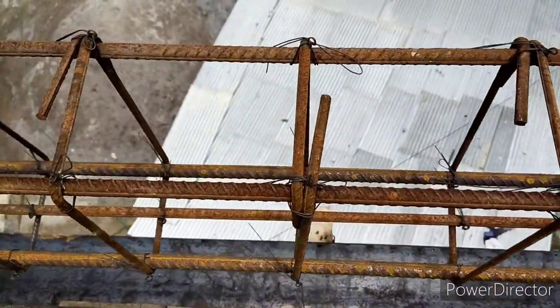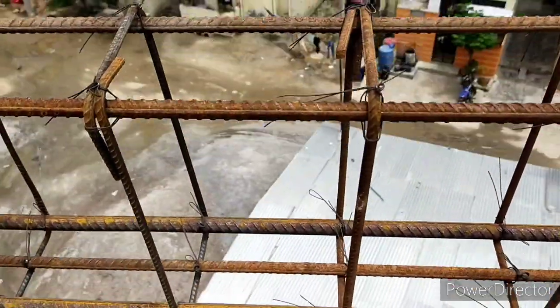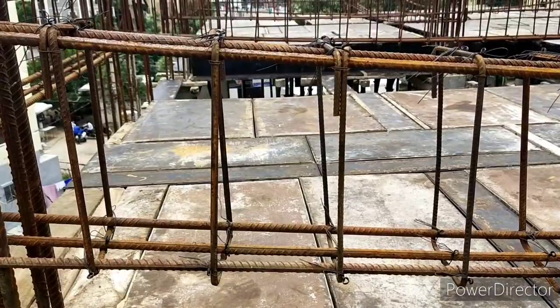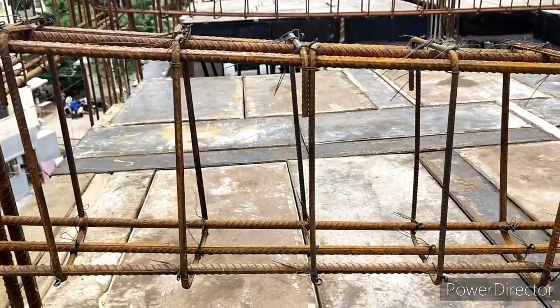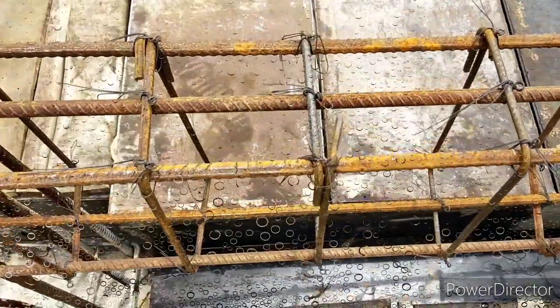These are single legged stirrups. Stirrups are of different types. They are single legged, double legged and four legged stirrups. These are used based on the cross sections of the beam or column, the number of reinforcement bars, and the load carrying capacity of the structure.